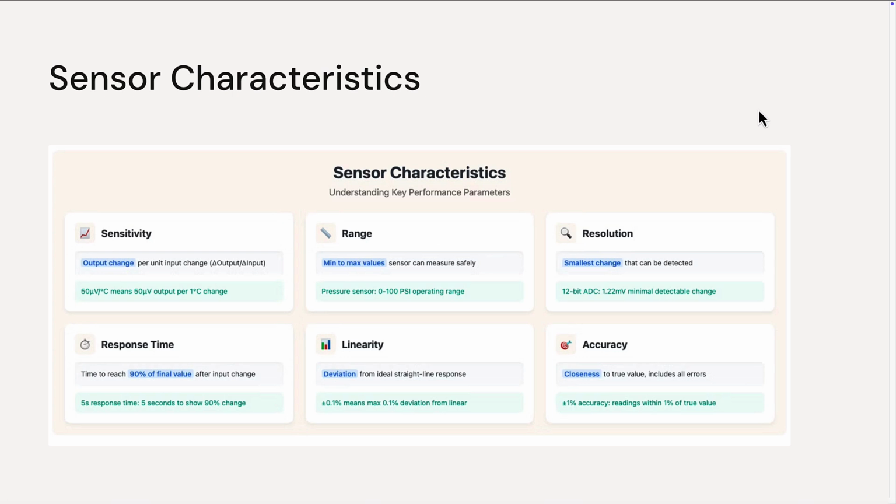Some of the laser scanners have a beam that can detect obstacles in a certain angle. Some lasers are limited to only 60 degrees, this is the field of view. That's a characteristic. This field of view could be 180, and some lasers see 360 degrees. But what differs? Now you are in front of me, so the angle is straight forward, so the angle here is 0.